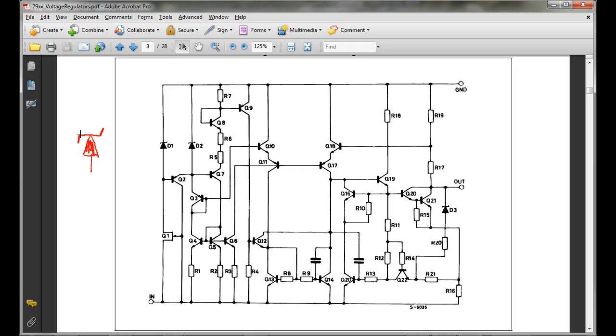But the problem is, I don't need to worry about this. All I've got to do is figure out, what does a regulator need? Well, it needs the input unregulated, it needs an output for regulated, and it needs a common, right? You understand? So these are all what we call three-terminal regulators. All you've got to do is figure out what their current is rated at and what voltage they're supposed to regulate at. That make sense?